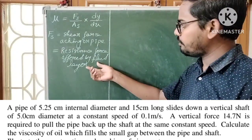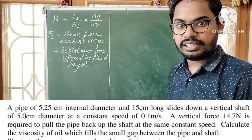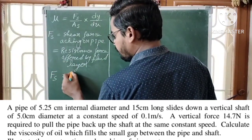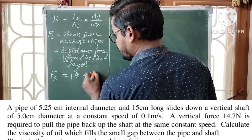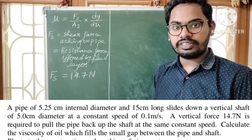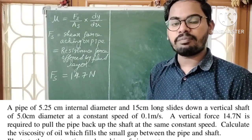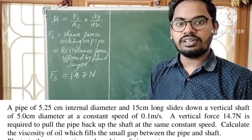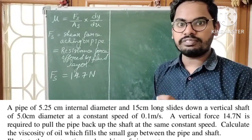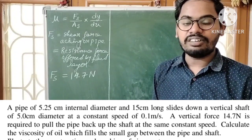That resistance force is equal to the shear force acting on the pipe. Here we applied 14.7 newtons. The resistance force offered by the fluid layer is equal to the amount of force applied on the pipe, because under equilibrium condition, the pulling force applied on the pipe is equal to the resistance offered by the fluid layer.